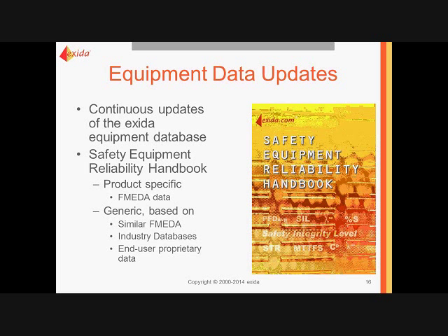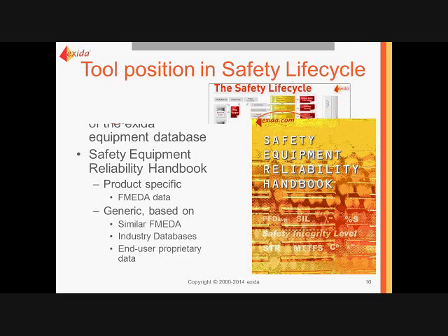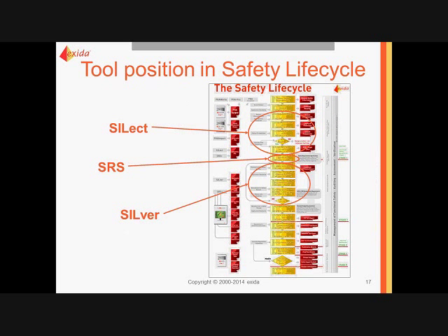So if we look at the tool position in the safety life cycle here, it's a little difficult probably to read the graph, but you can see that SELECT is used during the SIL selection and when you're doing the determination. exSILentia does have an SRS tool that helps you document and maintain your design information for your SIS and for each of the SIFs.